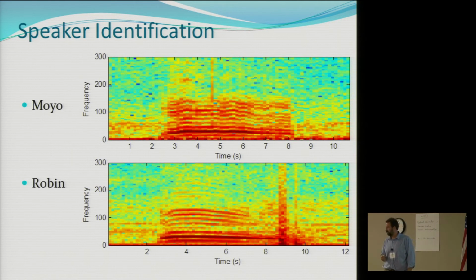So how do you decide what you're taking from each vocalization? We just divide it into frames, and in each frame we do an analysis, and that's the acoustic vector. The analysis would be spectral. Yes, you start with a Fourier transform, and it gets converted. A cepstral coefficient is basically the shape of the spectrum. That's a good way to think of it. It's not the spectrum data itself, but it represents the shape of that spectrum. And we do some normalization that has a huge impact. We don't use energy directly. We use normalized energy because you don't want to be affected by distance to the microphone, those kinds of things.